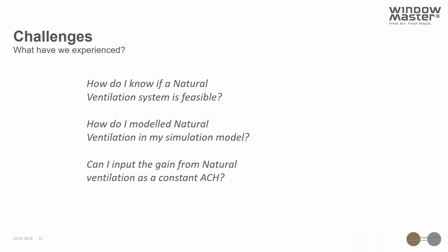Some of the challenges that we usually experience in relation to the simulations of natural ventilation systems are how do I know that the natural ventilation system will be feasible for the building that I'm designing? Because if you are investigating this in a dynamic simulation program, it can be very time consuming if you have to model a 3D model with different windows opening and test out different opening areas.